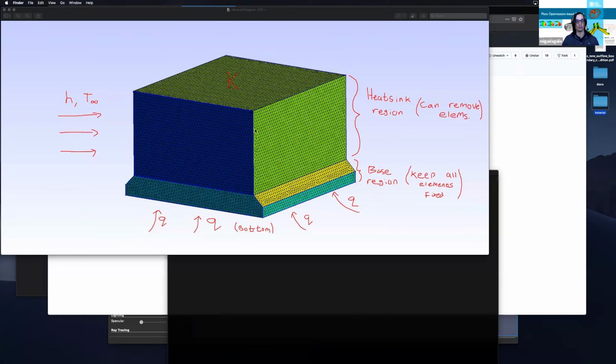Like what type of problem you want to do here? Because we can go on multiple levels. The easiest level will be, well, we can do first a steady state thermal problem. We can apply the heat flux. We can have a thermal conductivity. I don't know if there's an additional temperature that you want to meet. Are there any temperature boundary conditions here?